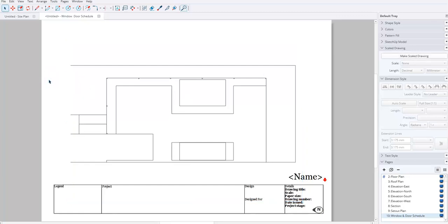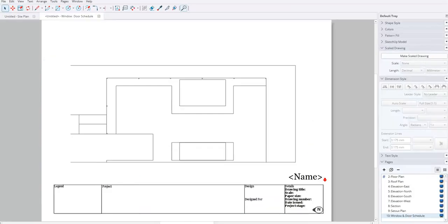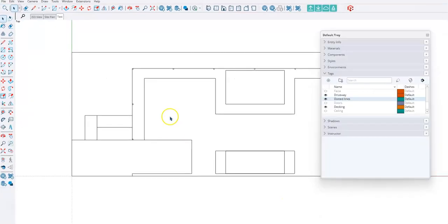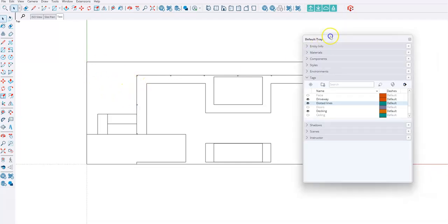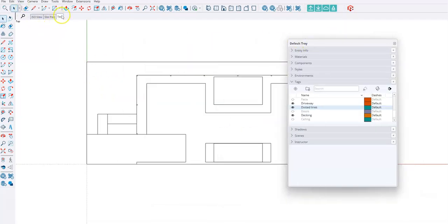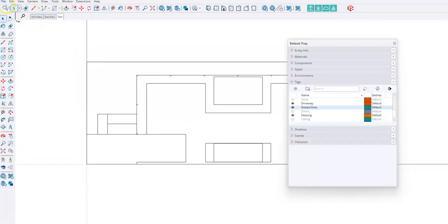Just have a quick look at it, see if I'm happy with it. Bounce back to SketchUp for a sec. Okay, so I can see a few things have been cut off. See over here? So I'm not happy with that. So what I'm going to do is zoom back out a little bit, and then I'm going to go Update. I'm going to go back into Layout and delete this one, and then I'm going to go back into SketchUp and just try that process again.